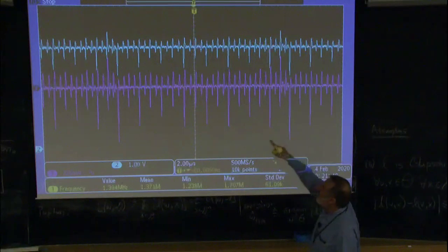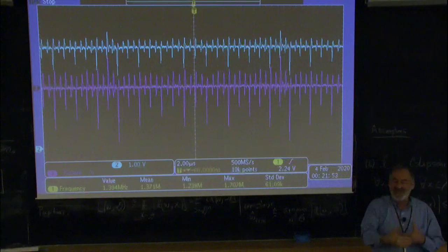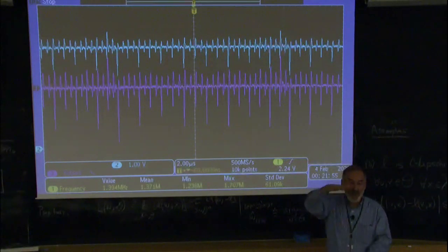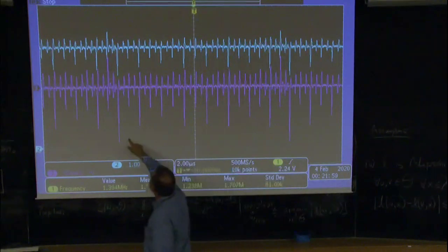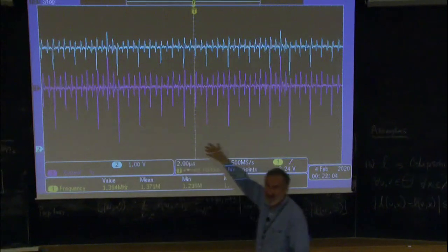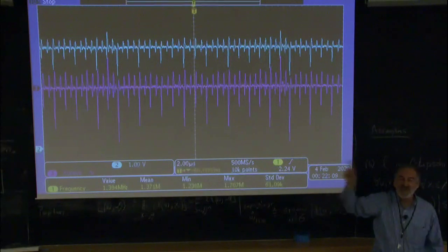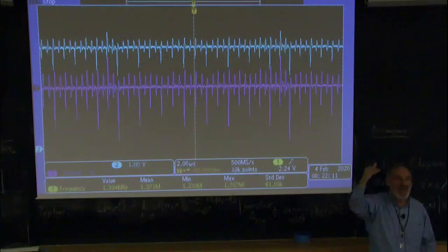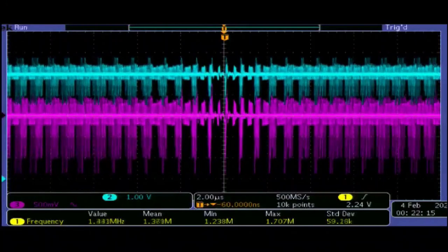In the middle, what I've done is I've switched my scope to an AC position, which puts a capacitor in and gets rid of the DC value, so I can blow up AC signals. And this is 500 millivolts per division. And you can see this spike is 1, 2, 3, 1.5 volts. That's really ugly. So what I'm going to do is put 1 capacitor between power and ground. 1 capacitor, I think it's a 0.1 microfarad, called a bypass cap or decoupling cap.